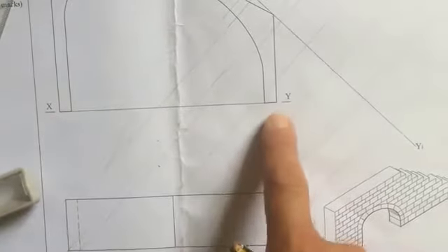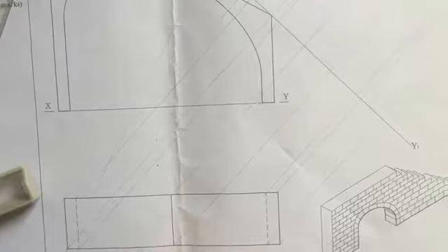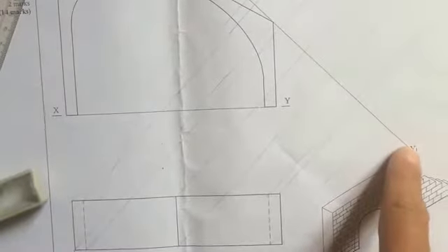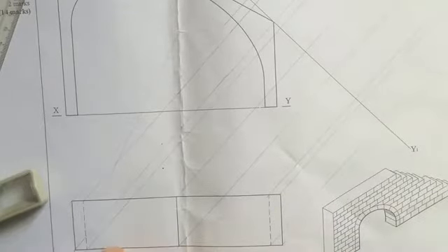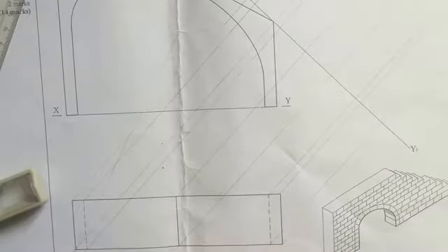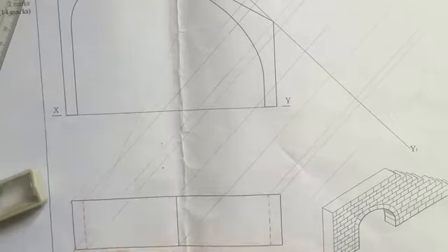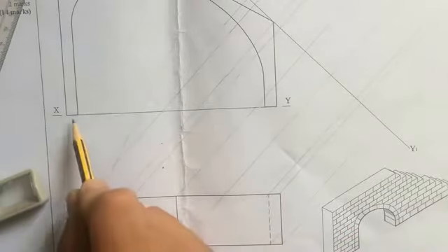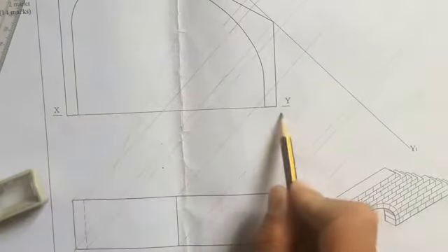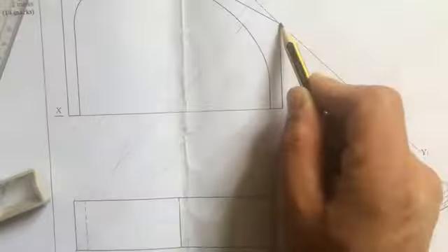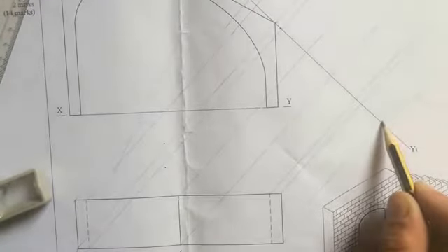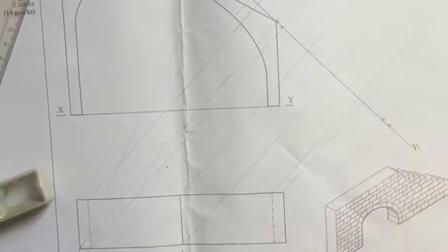Got the XY line in the front view, projection down here at 45 degrees, and the XY line where I want my auxiliary view. So I've projected some lines, and the first face we're going to see is the face down here because the arrow is down here. Now I can already set 1, 2, 3, 4 exactly on the XY line.